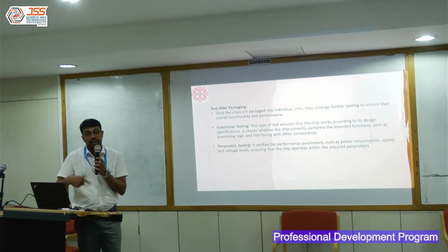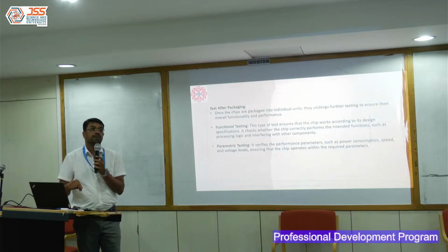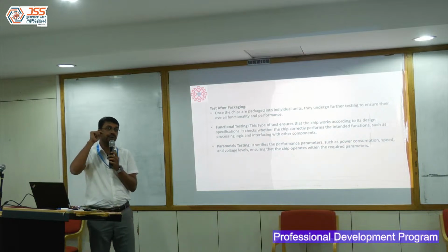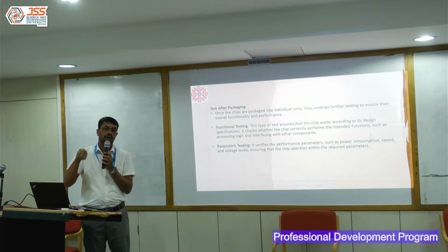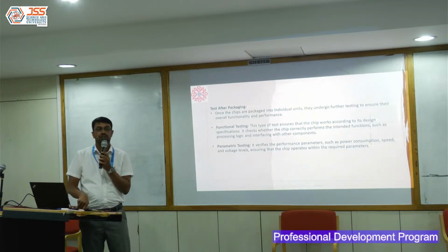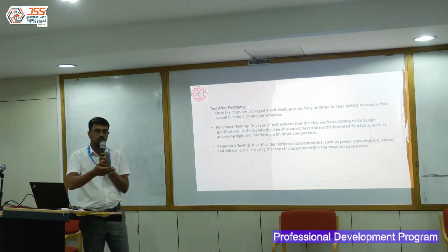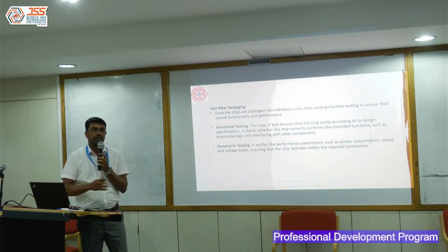He runs his functional patterns on that, because functional patterns take a longer time, as they have to verify each and every functionality of whatever has been built into that chip. So that typically takes a longer time. So they do the functional testing from their end. And to do this functional testing, you don't need this ATE and all. They can have a board, put that chip, and then start booting the chip and loading their programs.